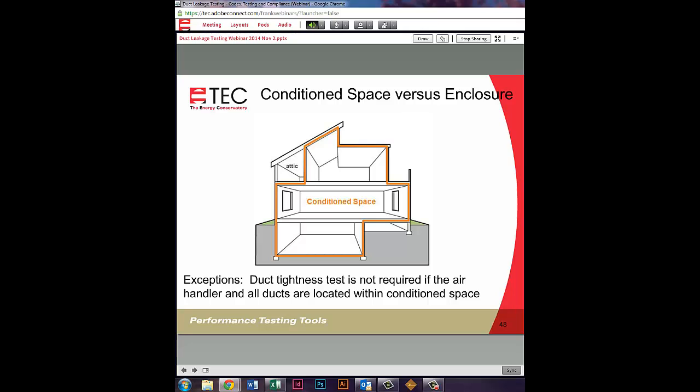That roof deck continues on, but they've made essentially a knee wall so that the attic insulation is going along the vertical portion of the wall and then makes a turn for the floor area, ceiling area on the left-hand side. The area where it's listed as attic, that's unconditioned space. So we want to try and get ductwork out of that location for energy savings.